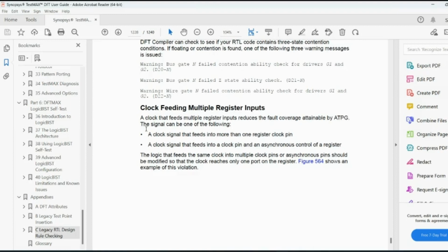If you disable that, and most of the time we disable it because we are not concentrating on tri-state, because tri-state might be a necessity as per the functional logic to create modules and functional blocks. Sometimes we need tri-state buffers. So that is needed functionality. As per functionality, if it is needed, you will have it in the design, and whether you want to check it or not is up to you.